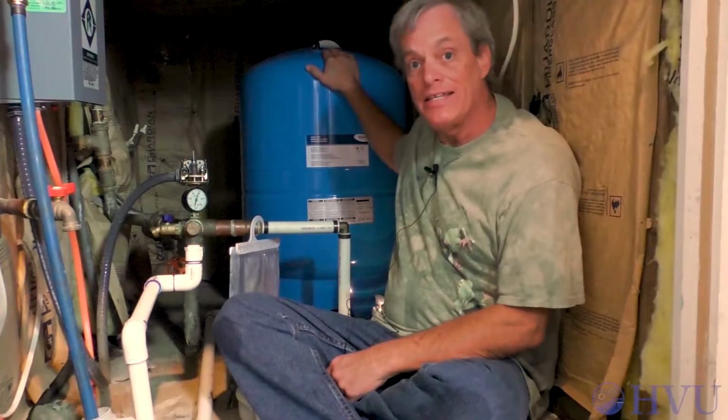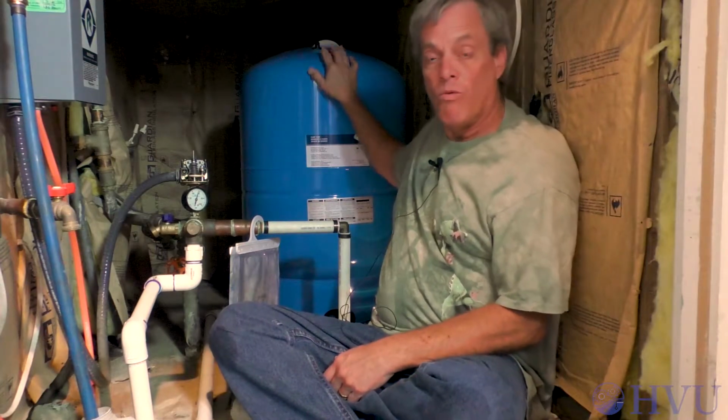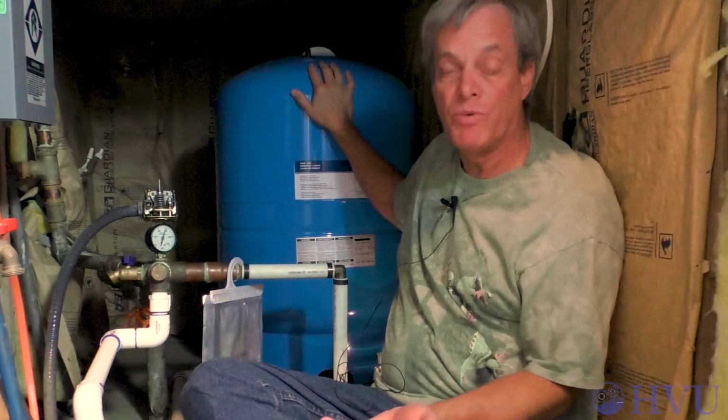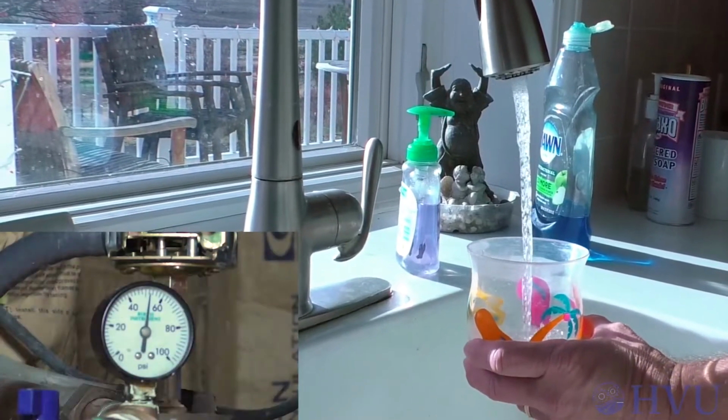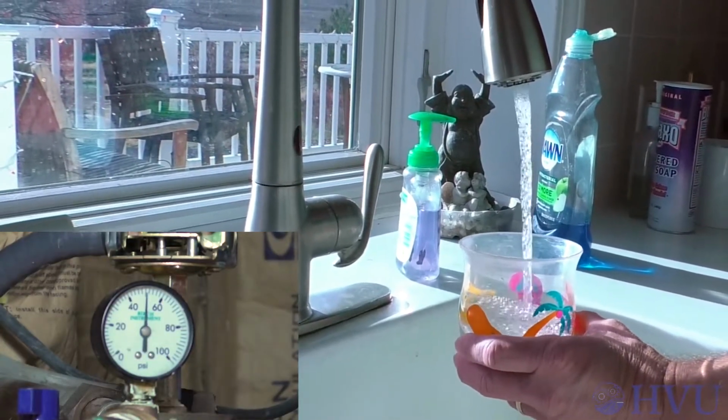My water's pumped out of a well. It's bad for your pump to turn it on and off every time you open a faucet to get a glass of water. The tank has an air bubble. When the pump goes on, the water enters this tank, which compresses the air bubble. When the pressure in the tank gets high enough, the pump turns off again. As I use water, the air bubble expands, releasing the stored energy.